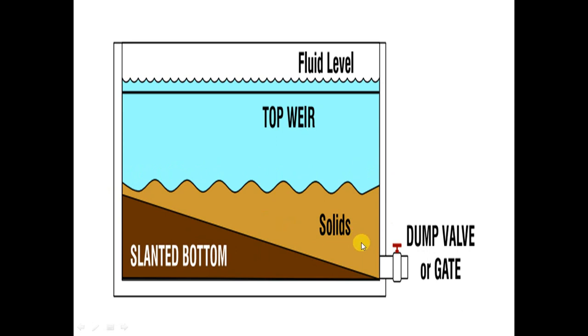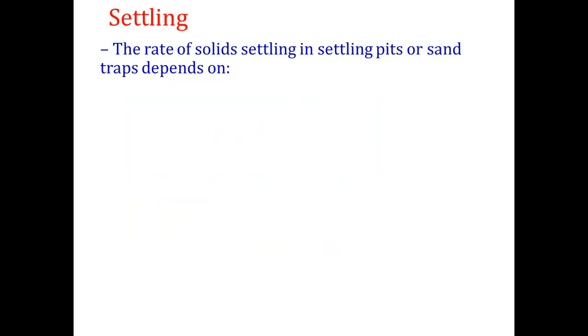And then once you see the solids are too much, after making the retort test, you can go ahead and open the dump valve and dump these solids and make dilution with fresh mud or base fluid. At this time, we are making a dump and dilution in order to keep the solids as low as possible. So this is very important equipment in dealing with solids control.